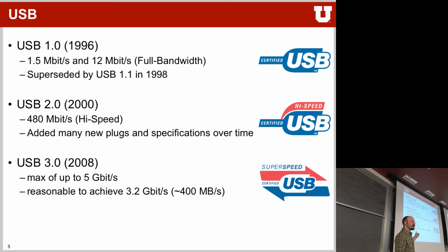There's another problem. At these kinds of speeds, signals become really tricky to deal with. It's really hard to make a system that runs at 5 gigabits per second, especially if you have to go through plugs and stuff like that. Your cable quality has to be right. The plugs have to be appropriate. Or else every little thing there can destroy your data rates.